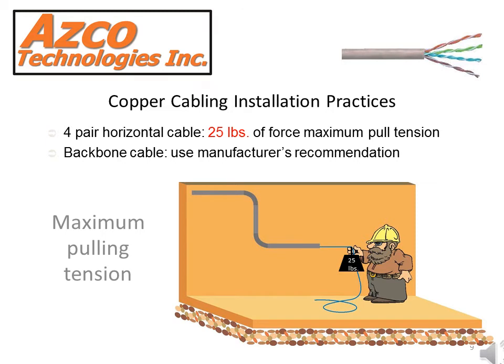Pulling tension. Twisted pair cables, again known as Cat5e or Cat6 cables, should have no more than 25 pounds tensile force pulled on them. Pulling any more than this will actually twist the pairs and damage the integrity of the cable, compromising its performance.